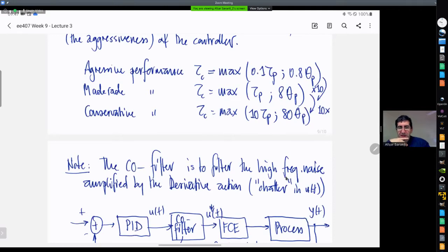But we also discussed that we have a new tool, which is the first order plus dead time model, which is a first order model supplemented by a time delay, a pure time delay. We can also extend this into a second order model, although we haven't focused on that.